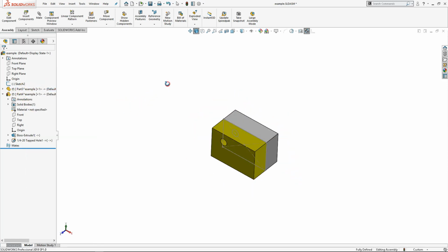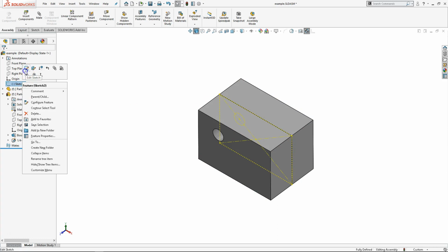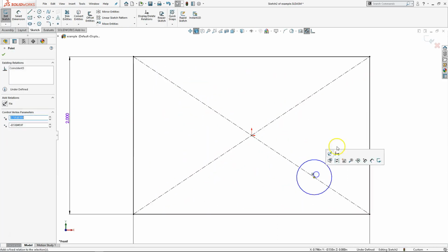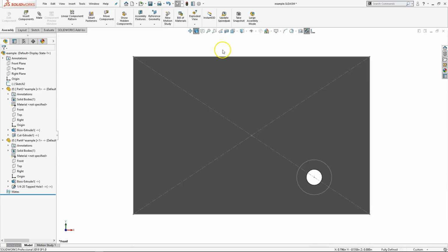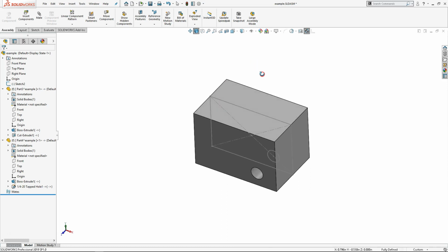All right, so when I show this component, those 2 items are tied to the sketch. When I want to make a change, well, I didn't put a dimension on it, so I'm actually going to have to drag it. I want this over here, and then we rebuild. My geometry follows it, and not just one, but both. So the advantage is I'm less likely to have mismatched holes. I'm less likely to have things not line up in assemblies, but I take responsibility for my model. Right? And all of those external references and everything that's being tied together, you're going up a level in complexity. You have higher expectations for the results of the model. Are we good? All right.